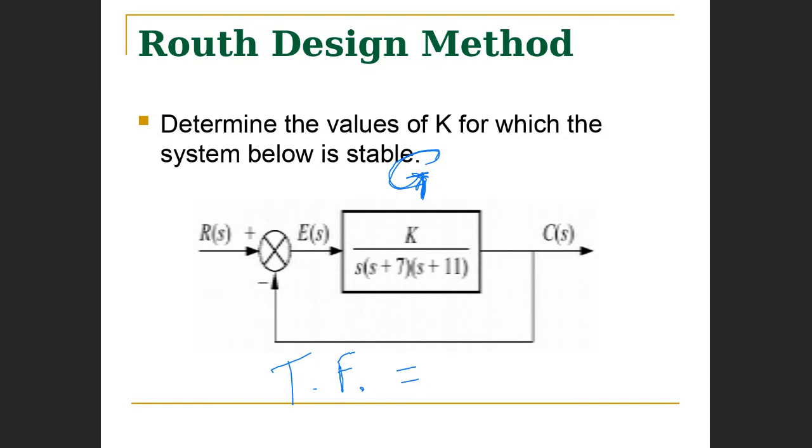So here it is. I'm seeing evidence of a threshold because I'm hearing all different kinds of things except the right thing. The week before last, we discussed the rules for simplifying a block diagram, and the last thing we looked at was the feedback loop. You should remember that to simplify this, if you call this entire block G, it'll be G over 1 plus G times 1, because it's a negative feedback and the feedback block here is just 1. But remember that if it was H, it would be GH. Remember that?